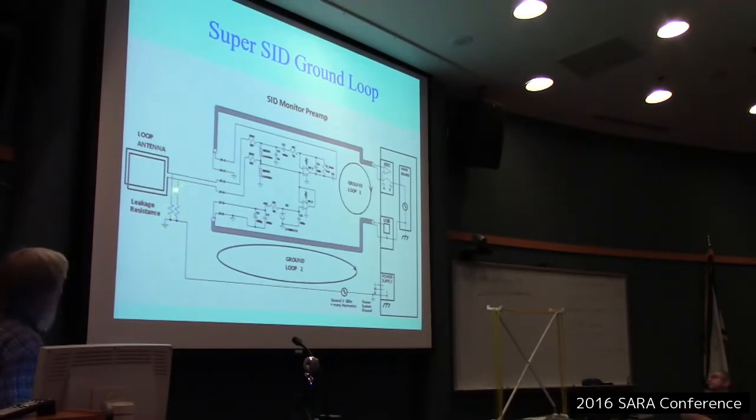And I think I'd heard one report of a little wet weather, and you started getting some 60 hertz hum in there. My bet is that there was some leakage path from moisture to these terminals to ground, and this ground is at a different voltage than this ground, and in comes the garbage there.